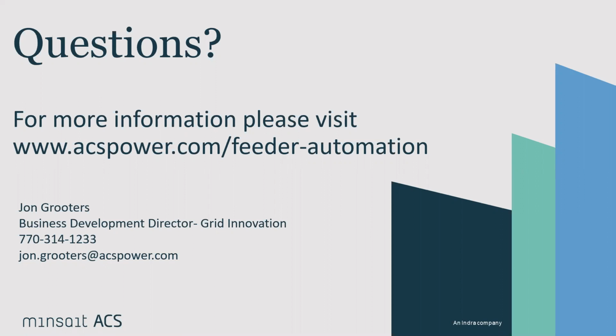Using it as a source, yes, we have considered it, and we do have some customers that are talking about doing some proof of concepts with this. The other part of it is, I'm assuming you're talking about a completely islanded situation from the utility. At that point, you would have to think about having a grid forming inverter along with it. So the answer is yes, it would be complex, but it certainly could be done if the infrastructure and everything was in place.